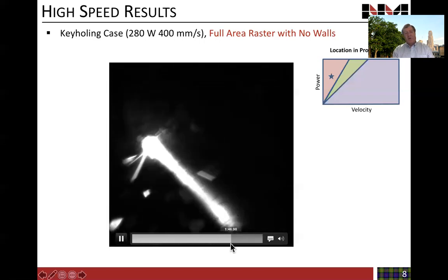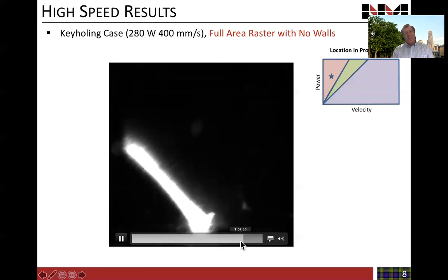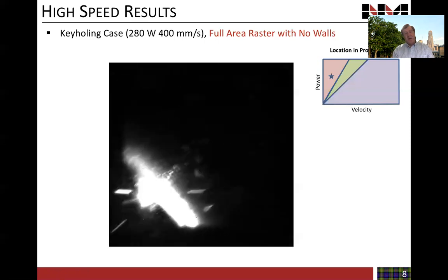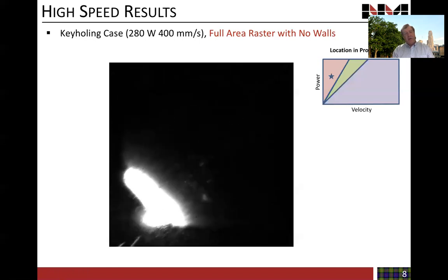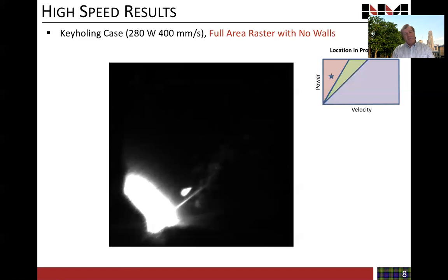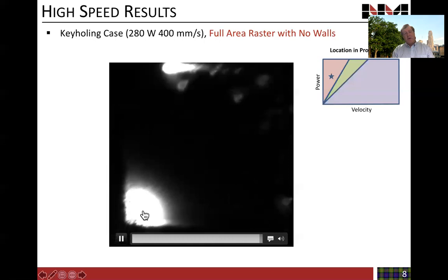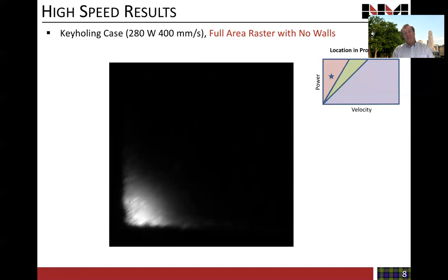As we approach the corner here, in fact, you can already see there's a problem. That melt pool is stretching all the way across the width of the specimen. And it is now one big glowing blob. And again, clearly in here, you're going to have different microstructure formation, lower cooling rates, for instance. Also, the potential of formation of keyhole porosity if you are not getting it already. That's what you get without walls.